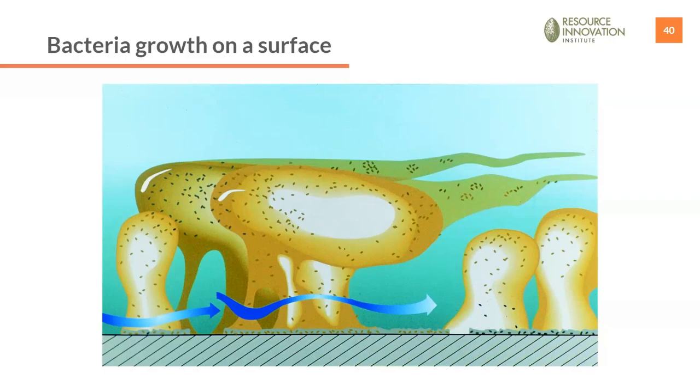And the thing I want to point out is these bacteria will stay adhered at the location where they start to form. The bacteria don't release and circulate through your entire irrigation system. So you need to have a disinfection plan that'll reach out and get to all of the areas in your irrigation lines. If you have a disinfection system that is protecting in just one area, it may not reach out and protect from bacteria growth across your irrigation line system. Next slide, please.